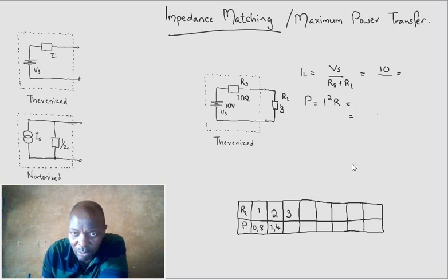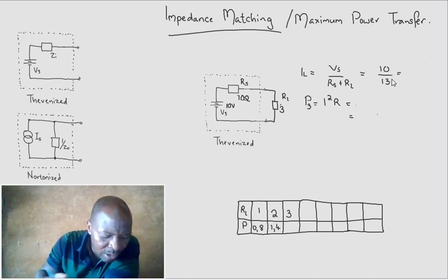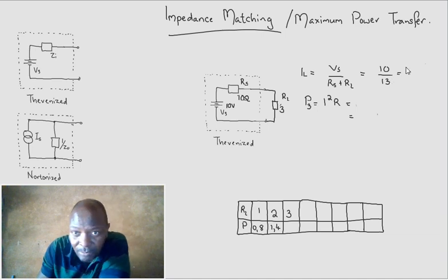Now, let's say you've got a new scenario where your power is what? Your power at 3 ohms is going to be, this is still 10, the system resistance, plus a load of 3, so it's now 13. 10 divided by 13 is going to give us something like 0.769. Less current. I'm only testing 3 decimal places.